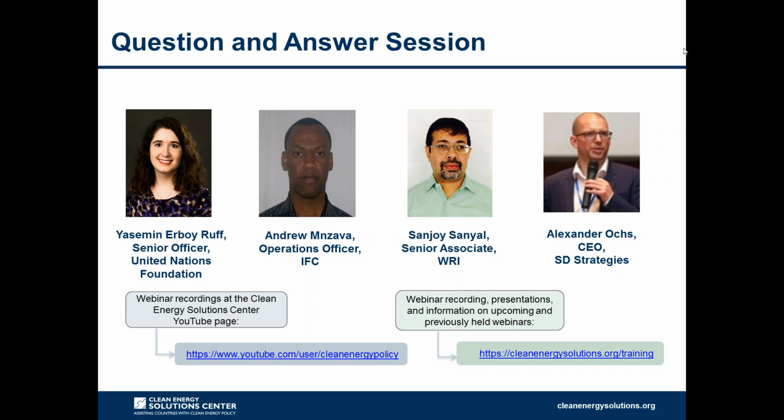Before you operate, for example, you pick a place and identify a location where you want to develop your mini-grid or microgrid. The first stage is to contact EWURA for them to give you a provisional license, if it is above 1 megawatt. If it is below 1 megawatt, all you currently need is registration.